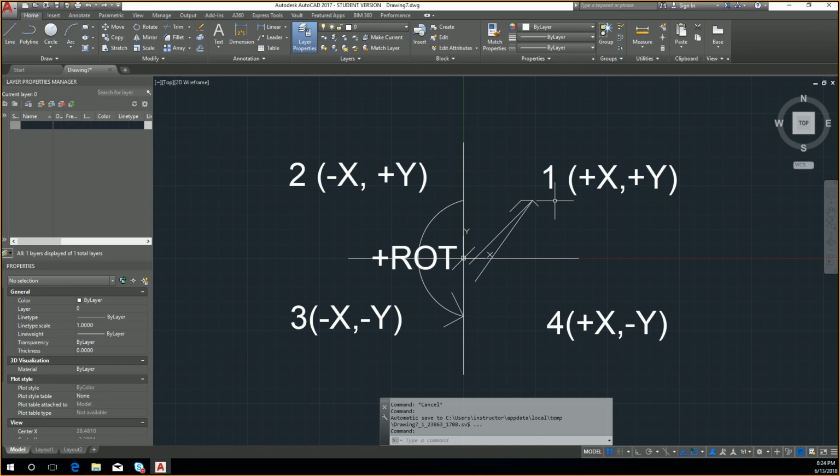The viewport control though is the freezing of layers, the freezing and unfreezing. The locking. I'm trying to remember what the locking does. Need to double check what the locking is. I don't use that one too often. The locking protects the layer, so you don't modify it by accident.